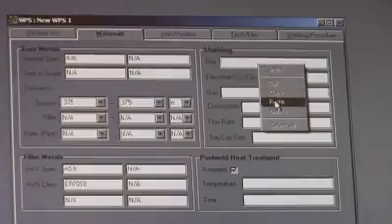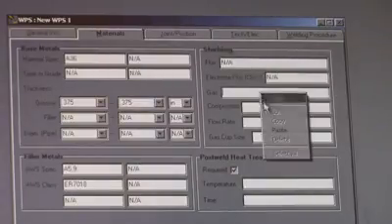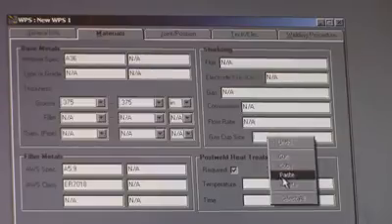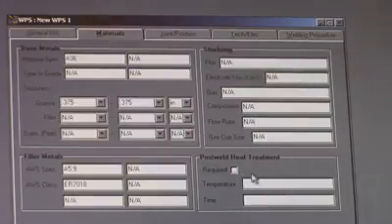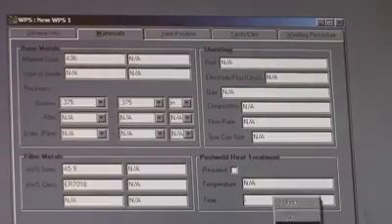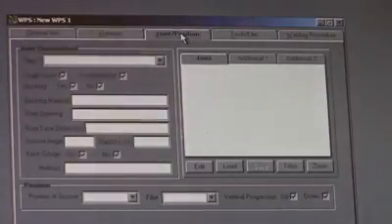Flux, that's for submerged arc. Gas for MIG, so we don't care about that. Composition of the gas, flow rate, again, we don't care. Gas cup size, we don't care. Post-weld heat treatment, we're not going to do any of that. That's sometimes required.